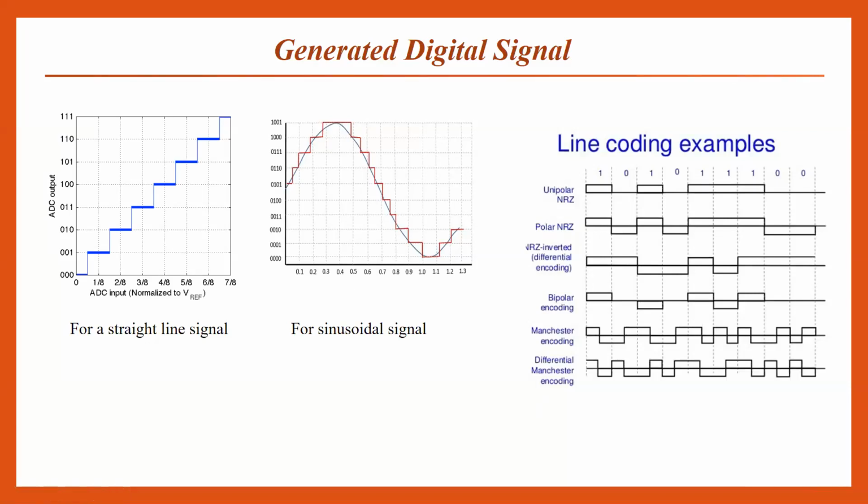So you will learn in your theoretical classes what types of line encoding there are and how this is done. I have shown you just some examples here, where the logical signal will be converted into an electrical signal. If we have done, for example, NRZ, and our sequence was 1010, then we will provide 5 volt for 1, 0 volt for 0, 5 volt for 1, 0 volt for 0. That means 1010 is converted into a voltage form.